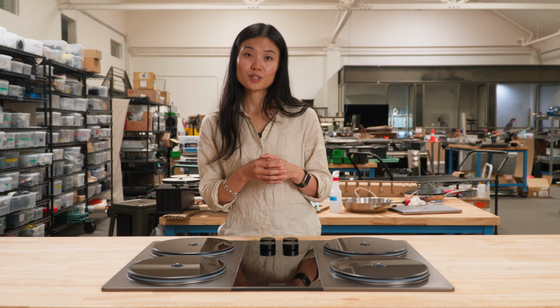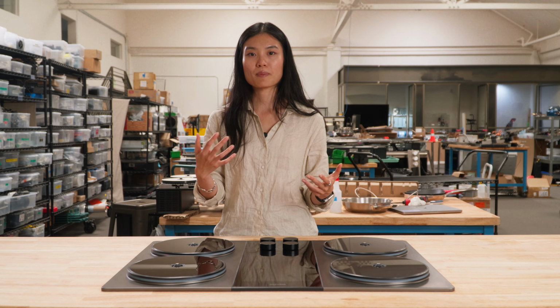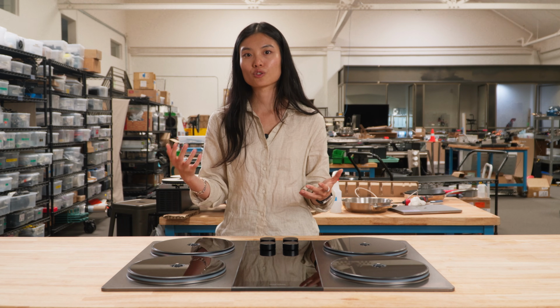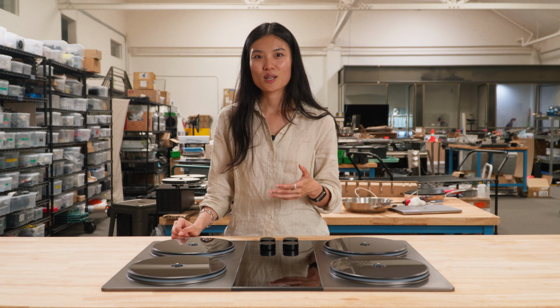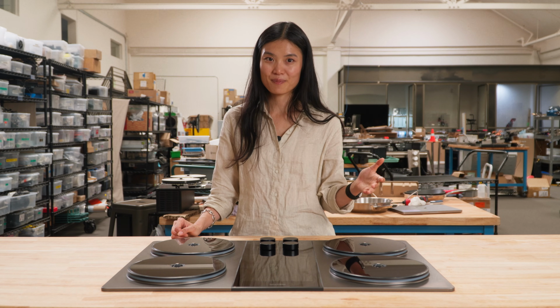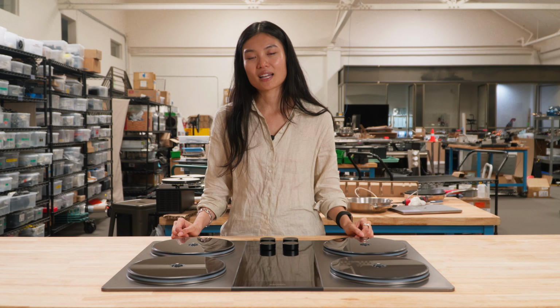The maximum available charging power depends on whether your cooktop is connected to 120 volt or 240 volt power. Charging time depends on both your electrical connection and your selected charging power. A 240 volt connection can recharge the battery faster than a 120 volt installation. Lower charging power settings will increase the overall charging time. For most households, the default setting provides an excellent balance between charging speed, battery availability, and electrical demand.